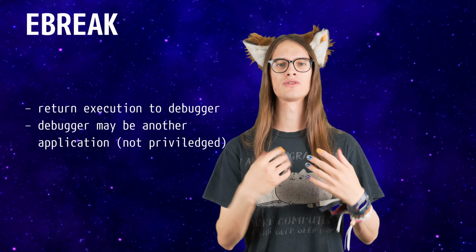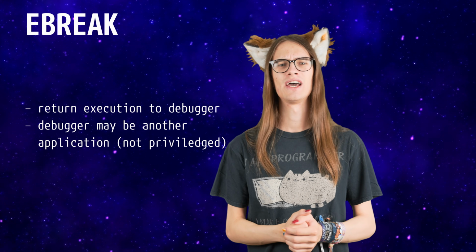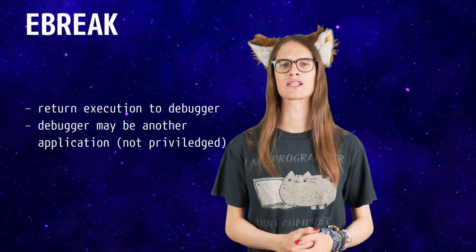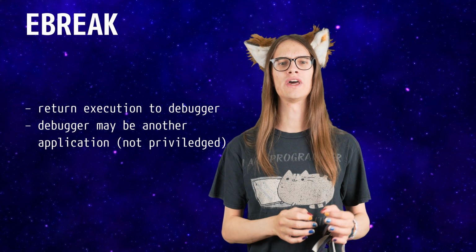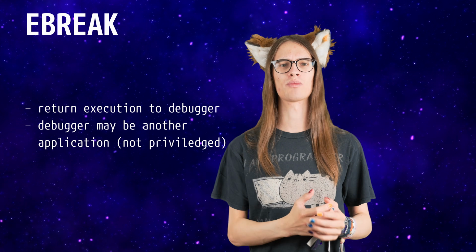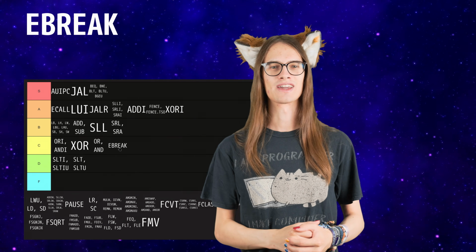The next instruction, however, is a different story. I once again really don't understand why it exists. I mean, it does have a purpose, debugger breakpoints. EBREAK is nothing more than a hardware breakpoint that returns execution to the debugger. Maybe I'm too stupid to understand how hardware debugging is implemented, and maybe I should read the RISC-V debugging specification. But I don't understand why this cannot be encoded in one of the many available knobs and needs its own special trapping instruction. C tier, I guess.